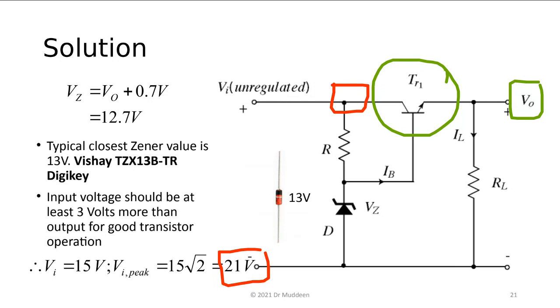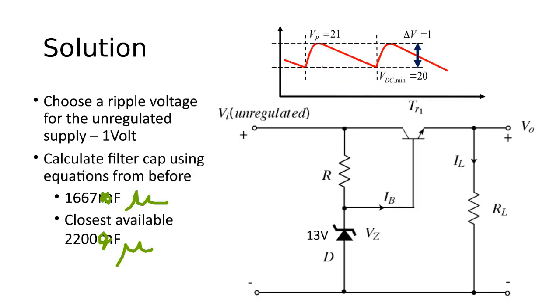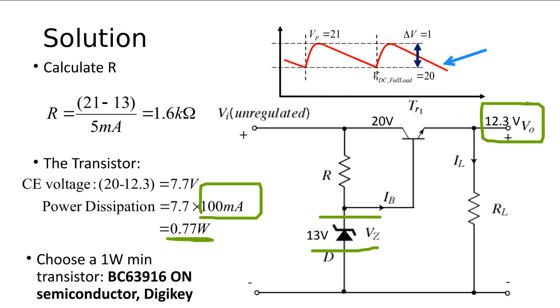If you were to go with less, like a 10 volt transformer, then you run into problems. Here we just follow the rule of thumb: for low voltage values, you want 15 volts DC. A 15 volt transformer will give me enough headroom, up to 21 volts, to comfortably supply that 15 volts DC should anything arise. But there's nothing wrong with being a little tighter if you want, bearing in mind what you might actually get to buy. Yeah?